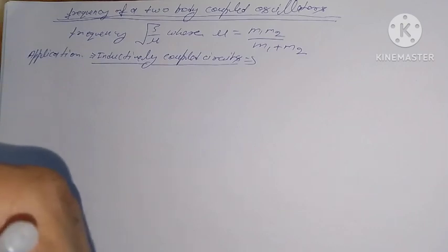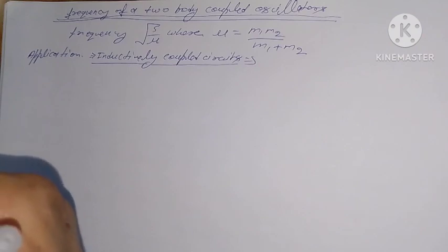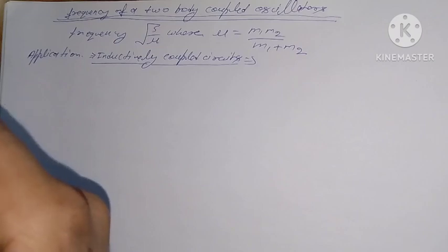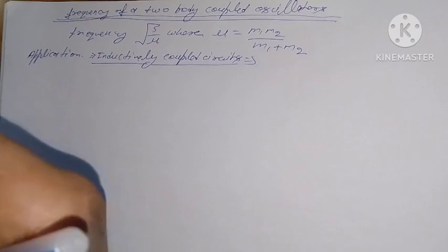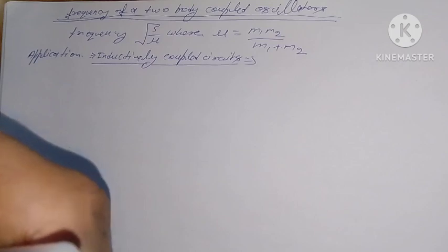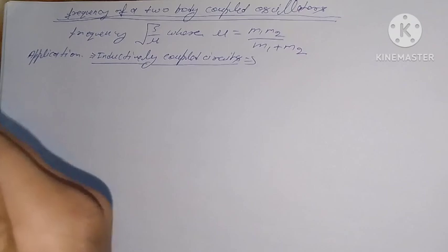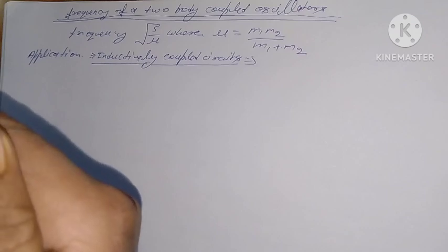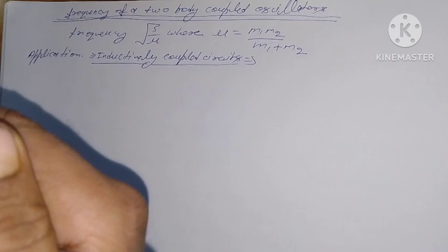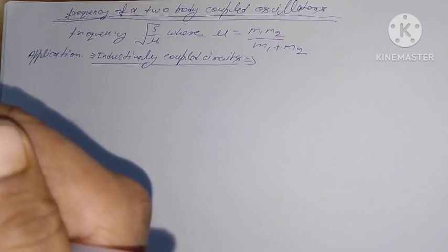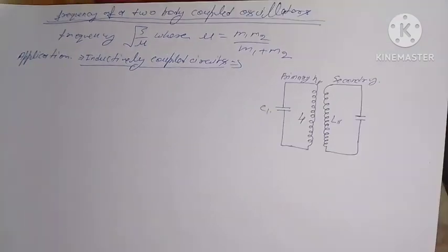According to Faraday's law of electromagnetic induction, whenever the magnetic flux in one circuit changes, an induced EMF is set up in the other, which is proportional to the time rate of change of magnetic flux, and lasts only for the time the change is taking place. The most familiar example is that of a transformer, whose working depends on the mutual induction between its primary and secondary coils.